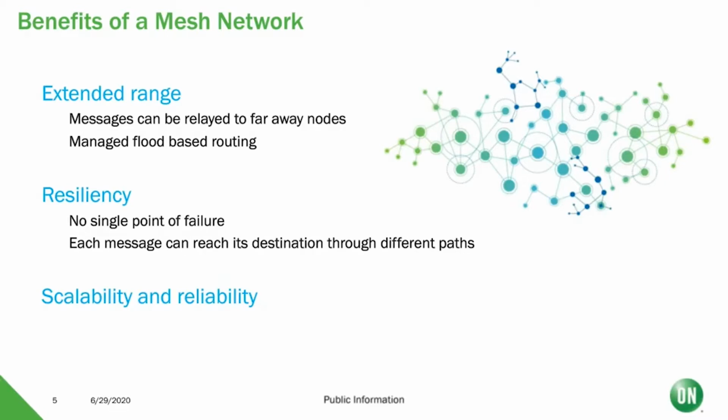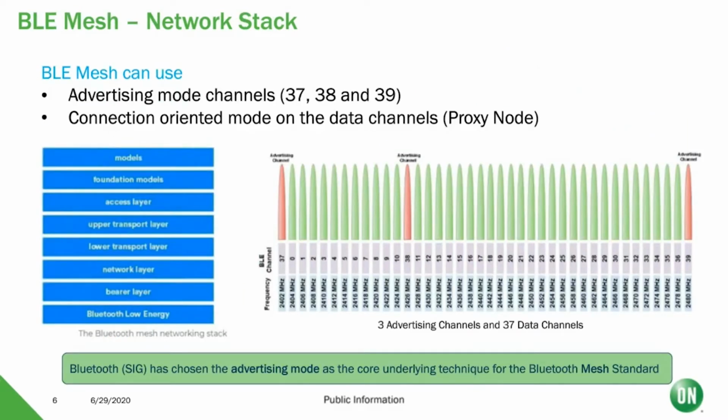And this is one of the reasons why Bluetooth SIG also started getting into the mesh networking side of things. So from a stack standpoint, for the next 5 or 6 slides, we'll dig deeper into the Bluetooth mesh and the protocol itself, how it is structured, starting with the physical layer. One key aspect is Bluetooth mesh runs over Bluetooth Low Energy. So implicitly, any device that supports mesh needs to have a Bluetooth Low Energy stack on it. And beyond that, there are multiple layers defined by the protocol itself.